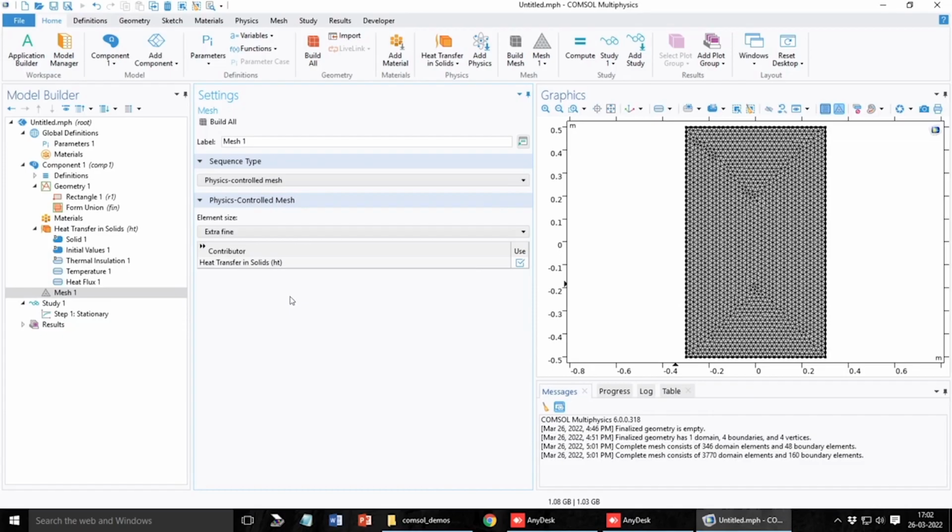But this needs a very clear understanding of, let us say, an approximate idea of the thickness of the boundary layer. That is where mostly these things play a big role, and whether the mesh size in those boundary layers is sufficiently small, and what the degree of resolution in the far field is, and all those settings. Okay, but for this problem, this level of refinement is good enough. I am saying this from experience, but you can also work it out yourself.